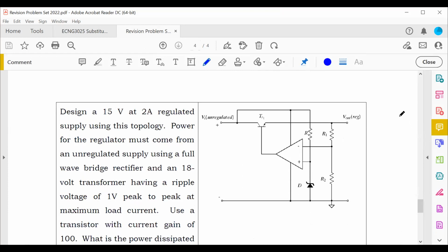Right, so what we do, just like we have with the transistor, we need a reference voltage. So we set the reference voltage using the Zener. And because of the virtual earth behavior of the op-amp, right now it's just working as a comparator. It's an open loop amp. Doesn't have any feedback resistors in it. It forces this point, because of the virtual earth, here has to be VZ as well.